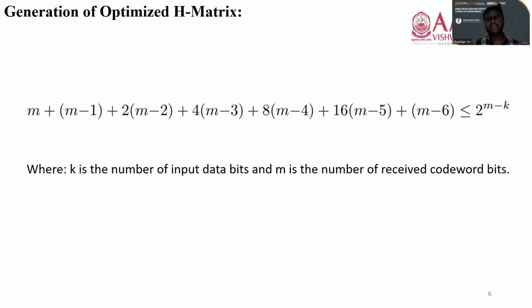Let's select an error. Let me select a 7-bit adjacent error. A 7-bit adjacent error says that 7 adjacent bits in the input data are corrupted. So how do we find the H matrix for that? First, we need to write down all the possible error sequences, like 1-bit, 2-bit adjacent, 3-bit adjacent, and further, all the errors that are possible in this 7-bit adjacent error.